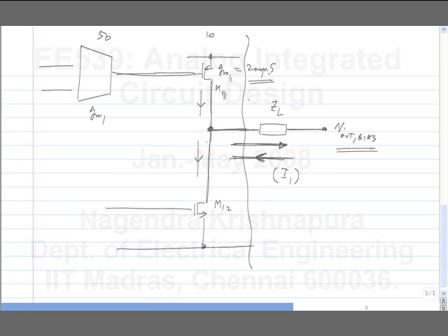What is the maximum current that can be pushed in this direction? No, that is the current that flows because of the load. But what's the capability? Actually, it is not limited like that, right? So this voltage can go down, depending on the swing limit of the first stage. It's not limited to I0 or anything like that, because this voltage can go down. So as this voltage goes down, depending on the characteristic of this transistor, the current here will go on increasing.